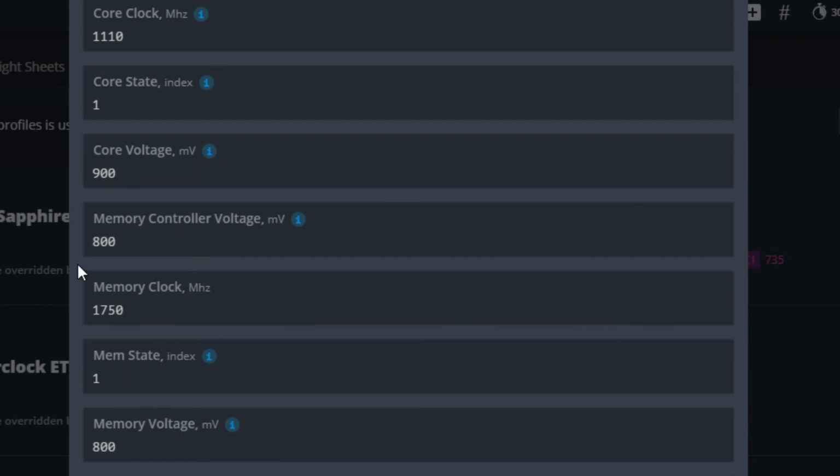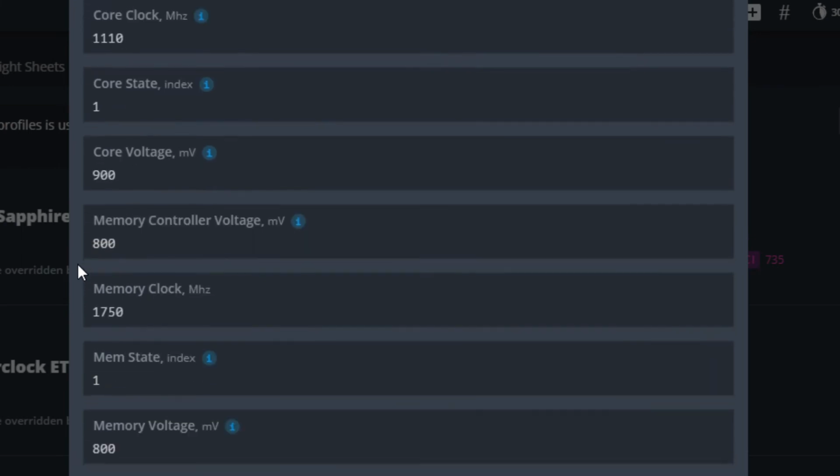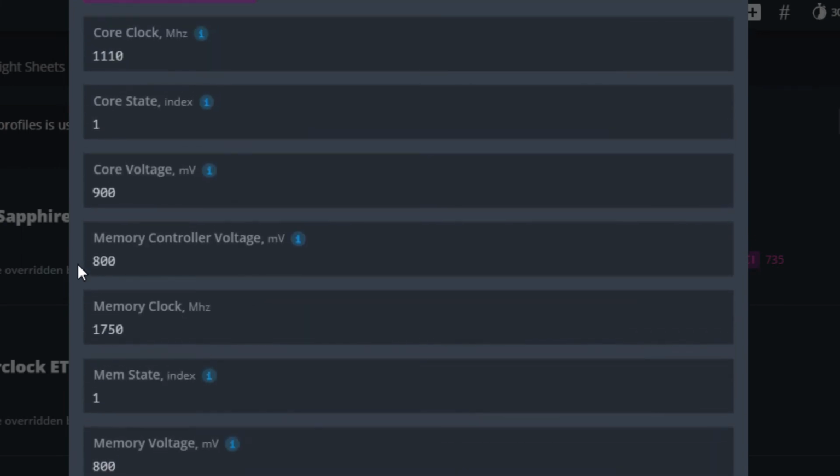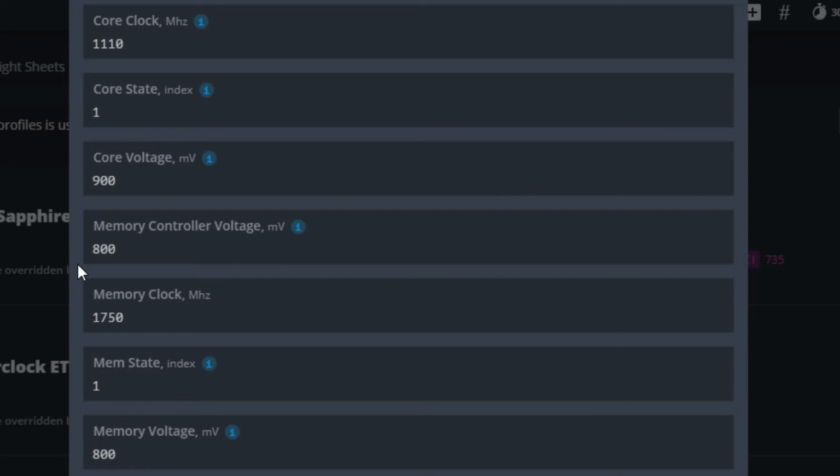But anyways, that's pretty much going to wrap up how I set overclocks for the RX 570. I hope this gives someone a little bit of insight, also a little bit more confidence to actually play around, go through the process of undervolting your GPU, getting a feel for, okay, this GPU here has good silicon quality. It can run at 800 millivolts for our given core clock there. Okay, I also have a not so good card where the memory, this is also a good note.